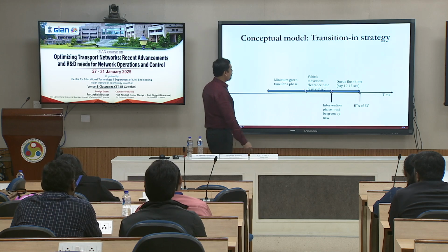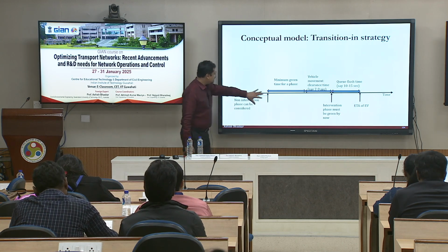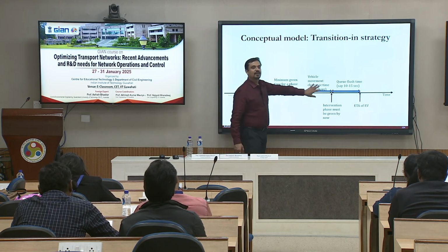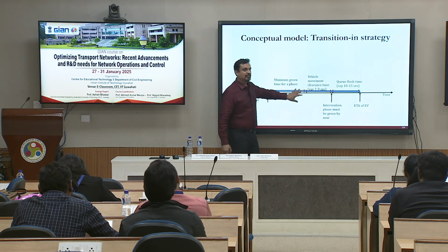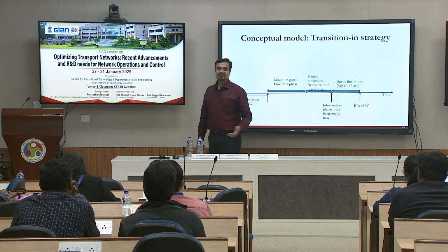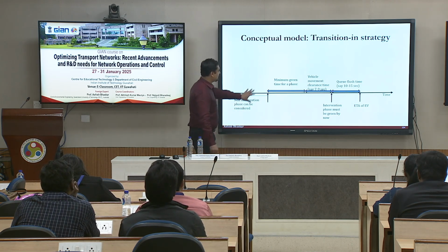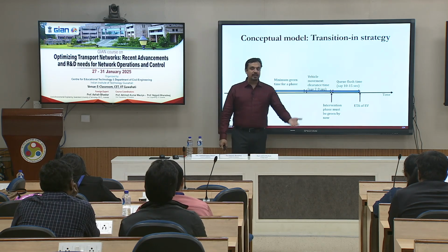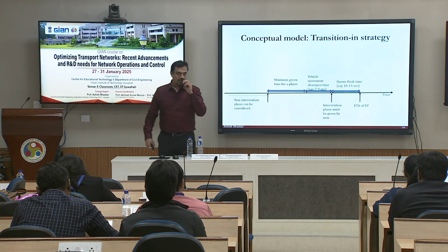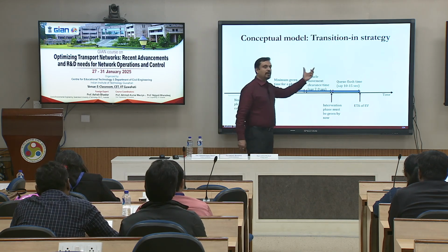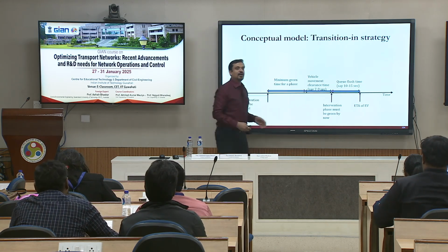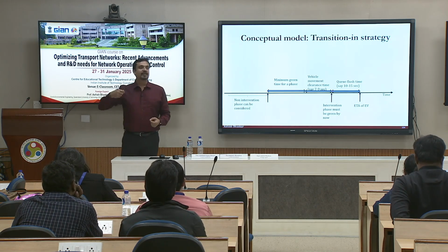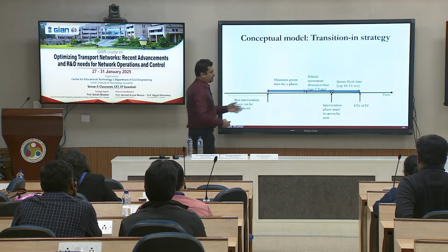Then you might think, if I am somewhere in this region in my current time, I still have scope to follow my current signal plan the way it has been designed, because you do not want to disrupt your system too much. So, if I am here I can still work around, and obviously there should be a minimum green I will be specifying to a specific approach, and there will also be some clearance time I will be specifying. So, you have some buffer attached to it, and these are the parameters for your EVP enforcement at the intersection, and that is how you will define it.